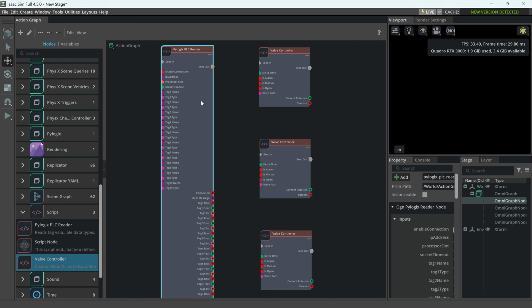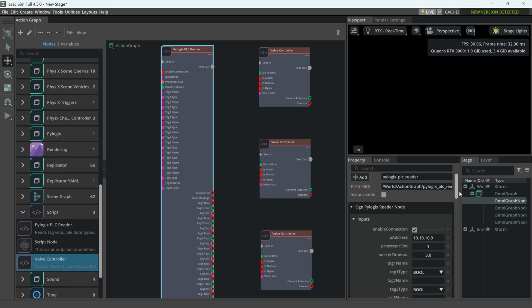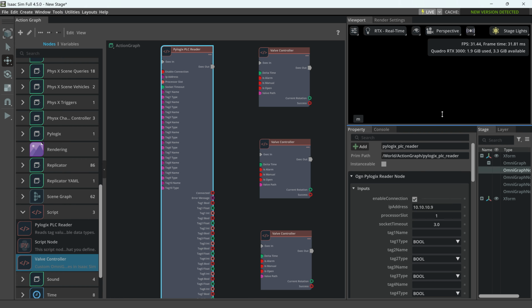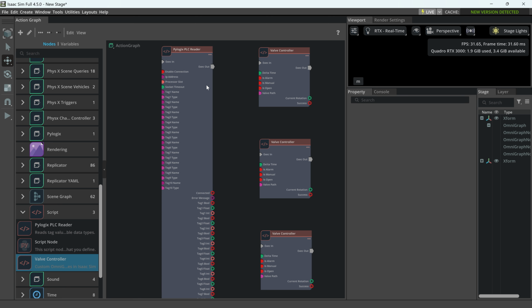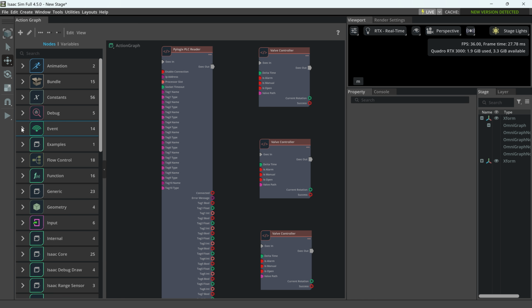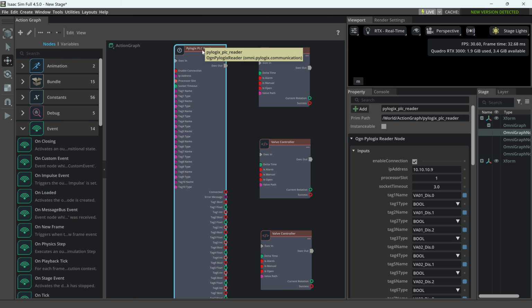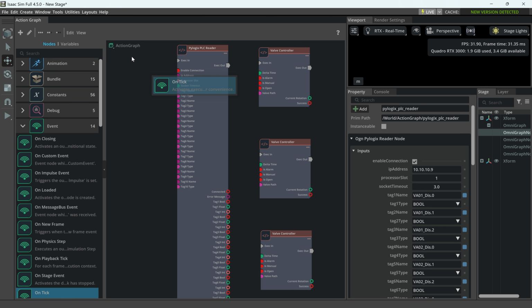It gave me a fast and simple way to connect to a Rockwell PLC over EtherNet/IP, which is perfect for rapid prototyping. In a real industrial system, I would normally use OPC UA for secure communication. But for this prototype, Pylogix lets me move quickly and focus on the architecture.